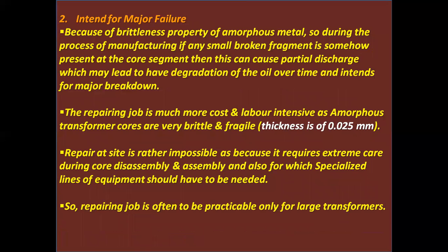Number 2, intent for major failure. Because of the brittleness of amorphous metal, during the manufacturing process, if any small broken fragment is somehow present at the core segment, then this can cause partial discharge, which may lead to degradation of the oil over time and end in a major breakdown.